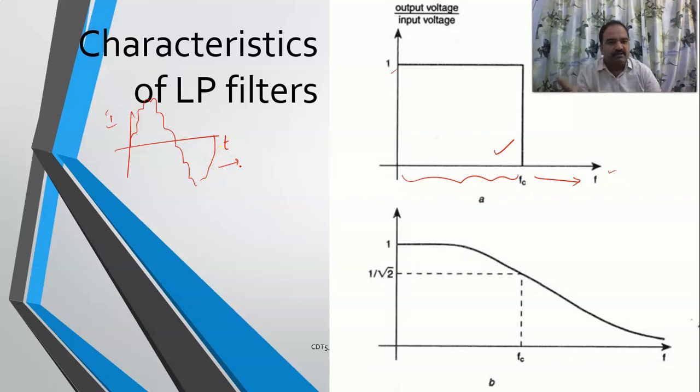This is a time domain signal. If I process it through some sort of Fourier transform, let us suppose this particular signal has multiple frequencies. 50 is the fundamental frequency. It also has 150, 250, 750, 850, 1150, and 1350, which means these are higher order harmonics. This is the fundamental harmonic, or we call it 1.